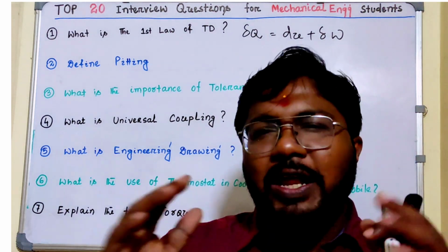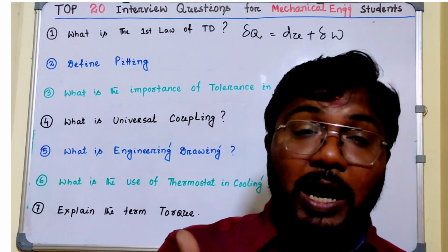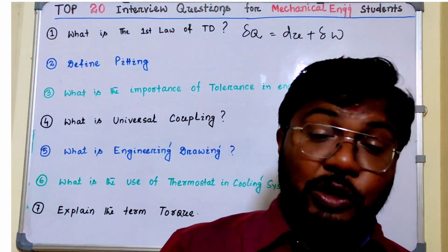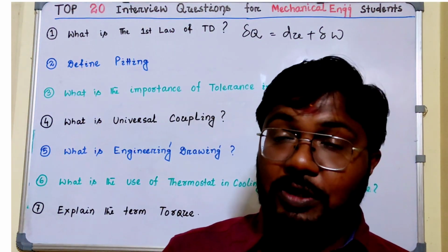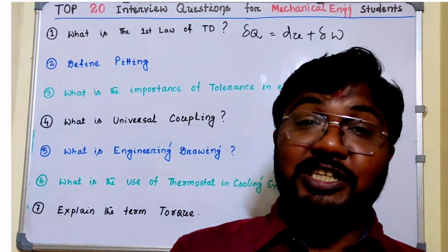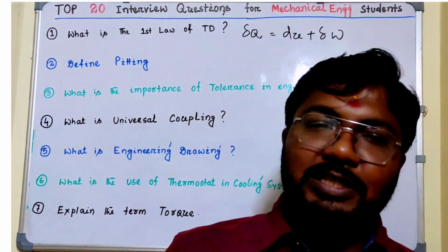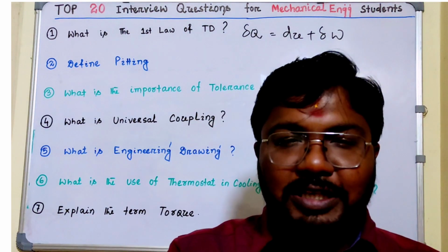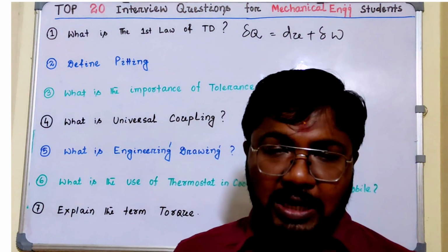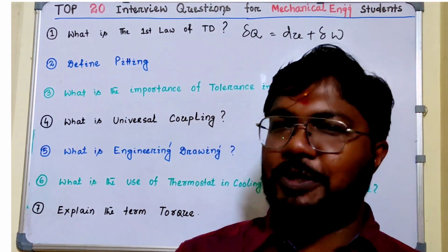It means whenever the engine is very much cooled, it does not allow the coolant to flow to the radiator. So the engine will easily warm up, and whenever the engine temperature increases beyond its design limits, the thermostat valve is opened and the coolant is transferred to the radiator, so the engine temperature decreases again. So overall you can say that it perfectly maintains the engine temperature for good efficiency.